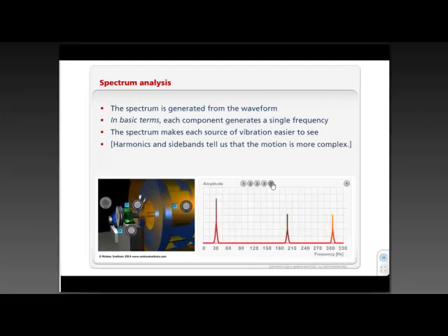And we can take it a step further, make it look a bit more like a spectrum. Here's our frequency down the bottom, and there's our vibration. So again, if we didn't have any bearing problems, we wouldn't see that there, and then the peak starts to rise up as the bearing fault develops. A nicely balanced machine, we start with a nice low peak there.